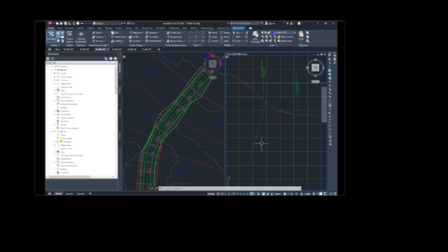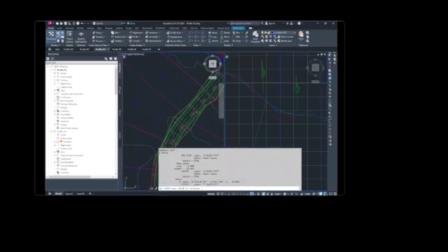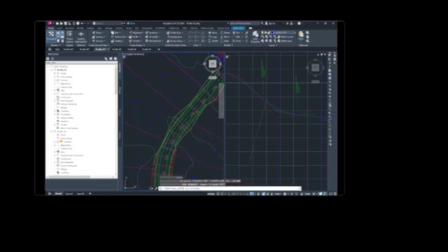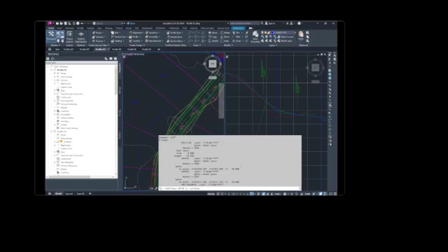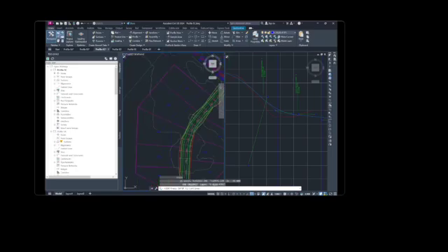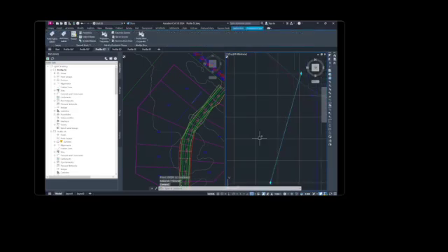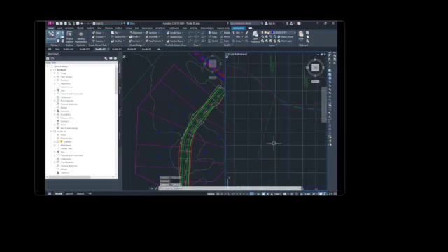Then when you check the 3D polyline and then list, the corresponding elevation of that is 28, because in the profile we dragged it down. Close.